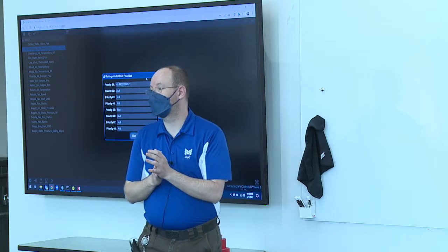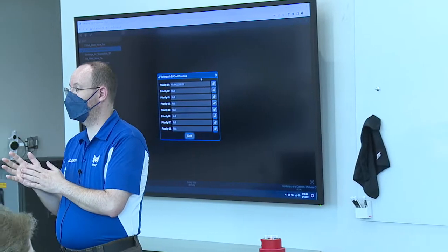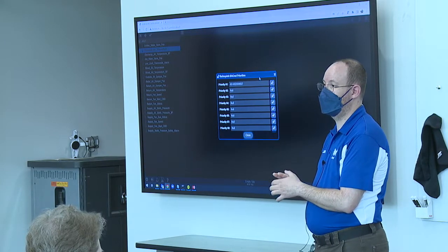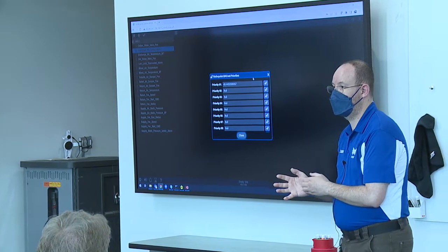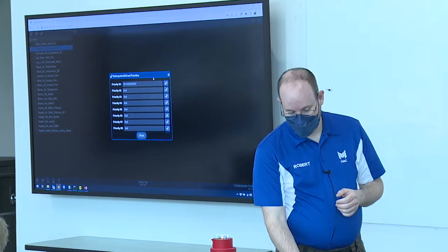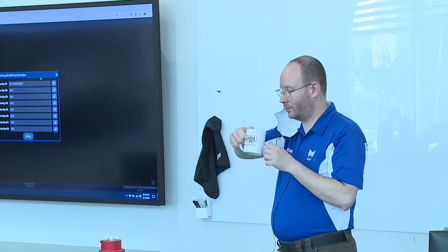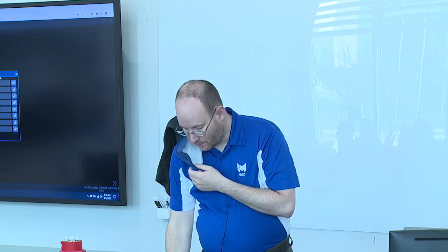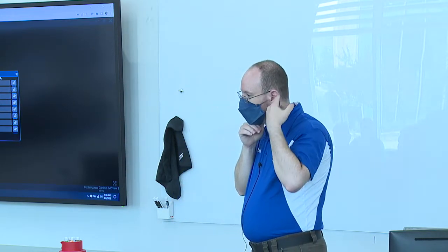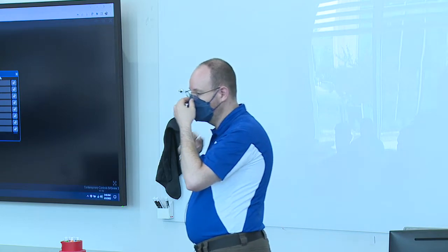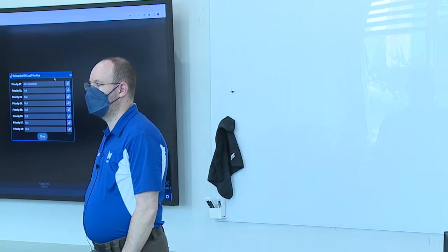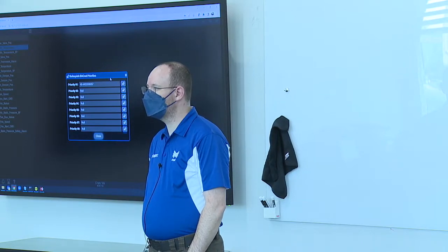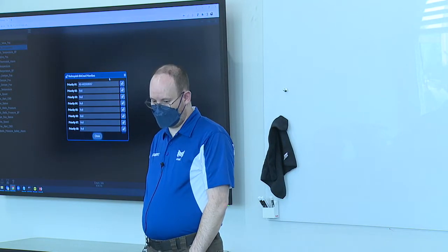Maybe it's the client conversation with the server where it isn't clicking. Could be. You have to realize that you're setting priority so that you don't have some idiot operator changing something on a controller from the front end. That's what you're isolating here. You can override it if you go into the controllers, put your own variables in and everything else. This is just a way, at a supervisory level, of not letting all the people that don't have a clue about chilled water setpoints blow up your chiller. The chiller killers. This is what it's all about right here.